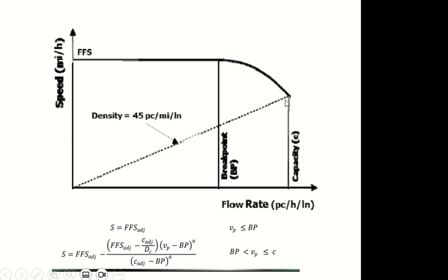If I want to find out the speed of the road in this section, then I have to use this big, scary, complex equation. We know the meaning of free flow speed. C means capacity of the road. This point. We have equations to find this point, but I'm talking about this point. So C means capacity. DC is called critical density.